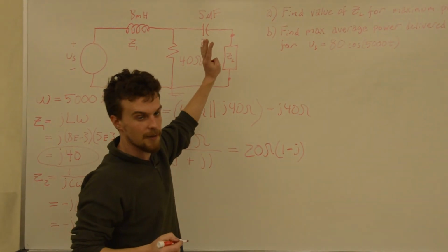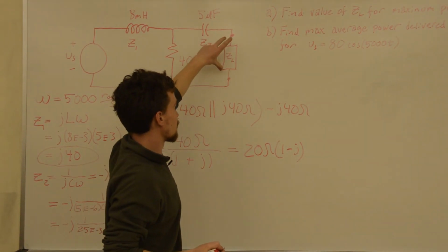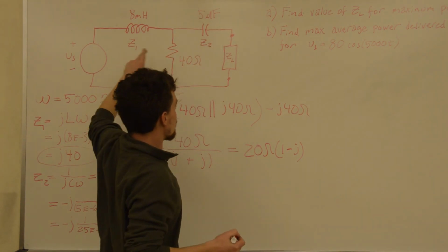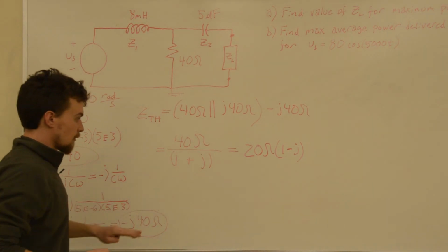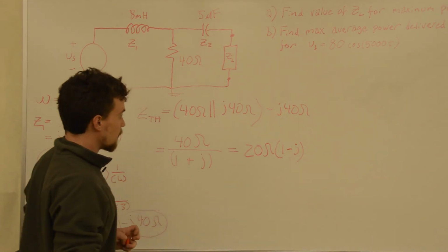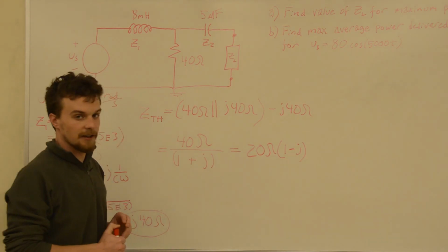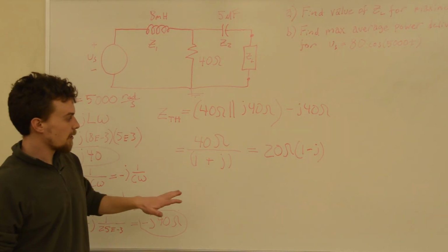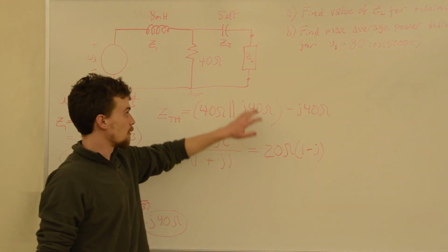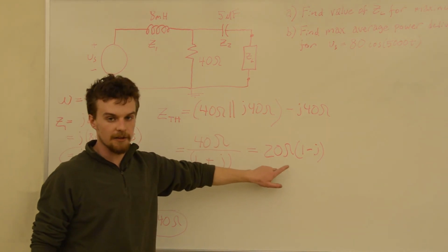We can just imagine that the load impedance isn't there; we're just looking for the impedance between these two points without it. Now, it's not exactly like the resistive rule. For maximum power transfer, your load impedance has to be the conjugate of this number.